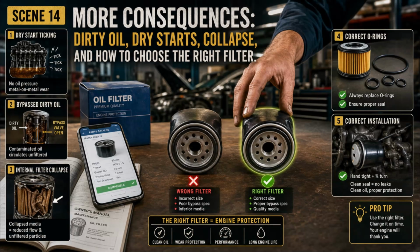Then compare the new filter to the old one, but do not rely only on appearance. Check the thread, gasket location, height, and overall shape. For cartridge filters, make sure the included O-rings match the ones you remove and replace them in the correct grooves. Avoid close enough filters. If a filter screws on but is not listed for your engine, do not use it. The hidden details are exactly the details you cannot verify just by looking. And finally, buy from a trusted source. Poor quality or counterfeit filters are a real concern in some markets, and a cheap filter is not cheap if it costs you an engine.